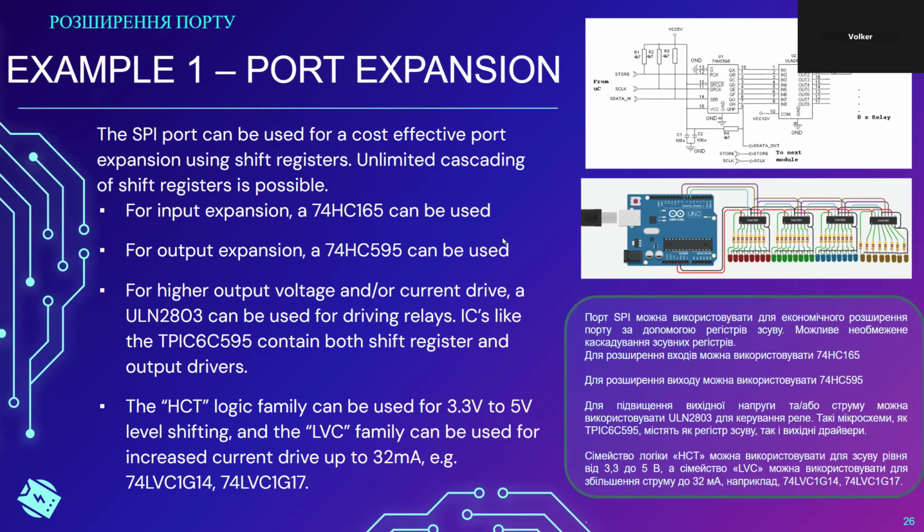There's one thing that I want to add. If it's a DC motor, then it would be very easy to not just turn it on and off. It would also be very easy to speed control it, because every microcontroller has a PWM output. The way a DC motor is typically speed controlled is by using PWM. Sorry, PWM means pulse width modulation.